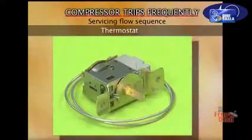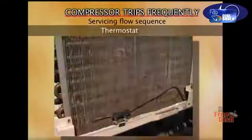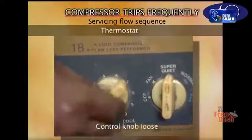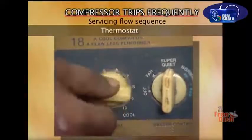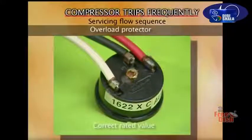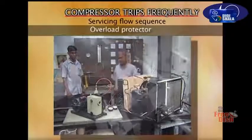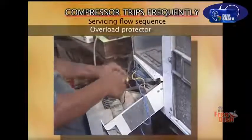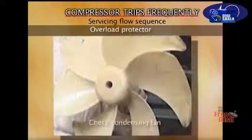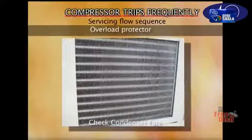Servicing flow sequence for compressor trips frequently. Check the thermostat. The setting is in the low range. Thermal bulb location, or there could be just the control knob is loose. Check the overload protector. Correct rated value. Check the suction and discharge pressures. Check the wiring. Check for leaks. Check the condensing fan. Check the condenser fins.